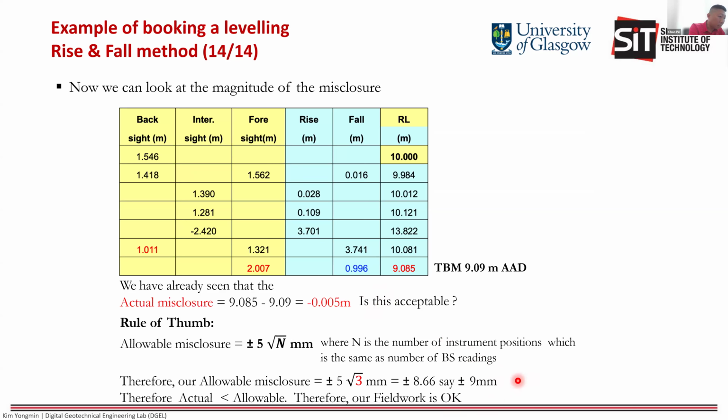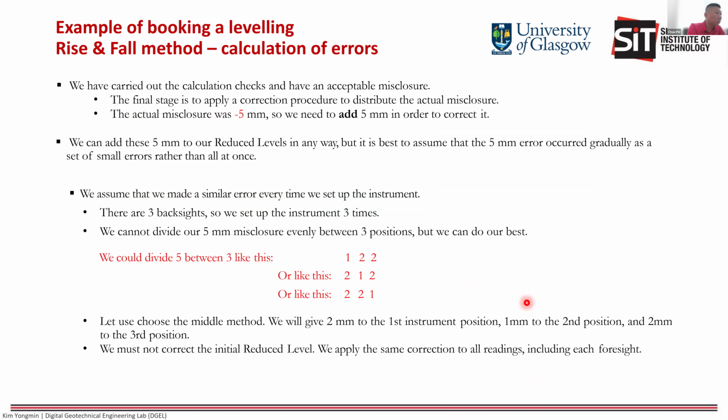Otherwise, if let's say the error is more, let's say 10 mm, more than 9 mm, then you may need to go back and do the survey again because the error is not acceptable.